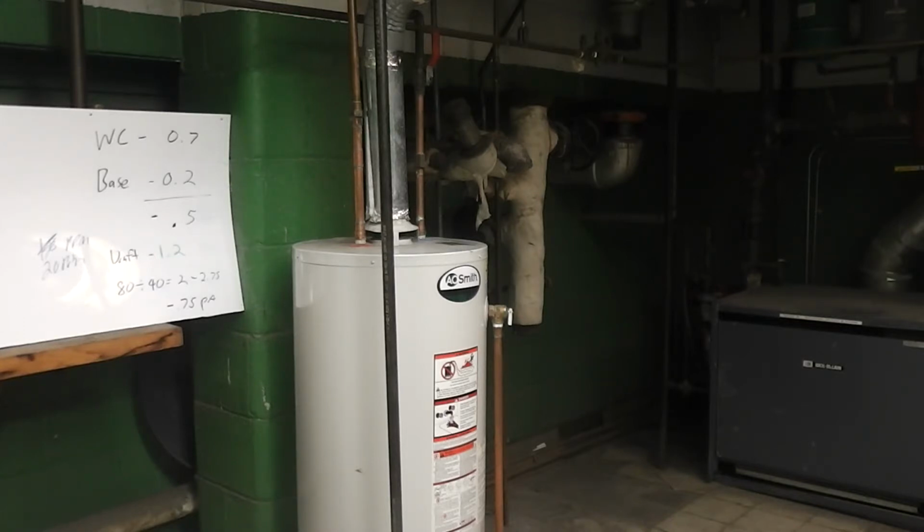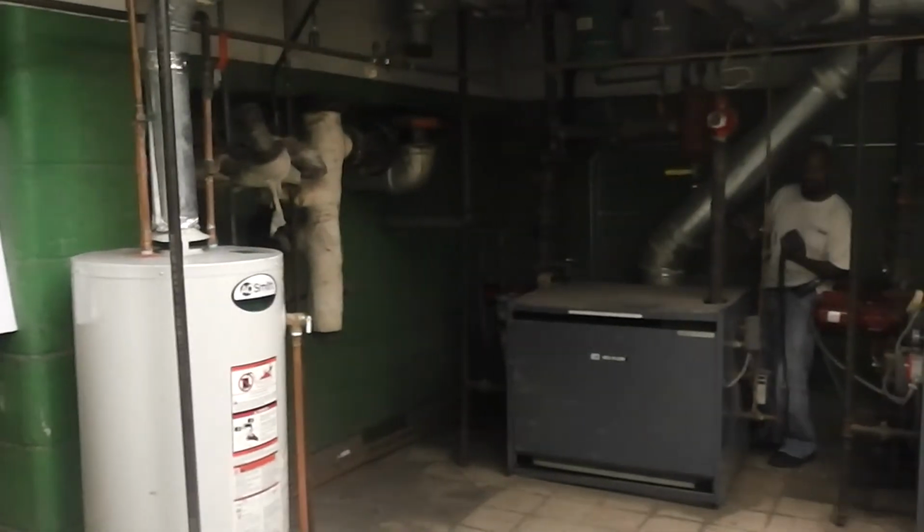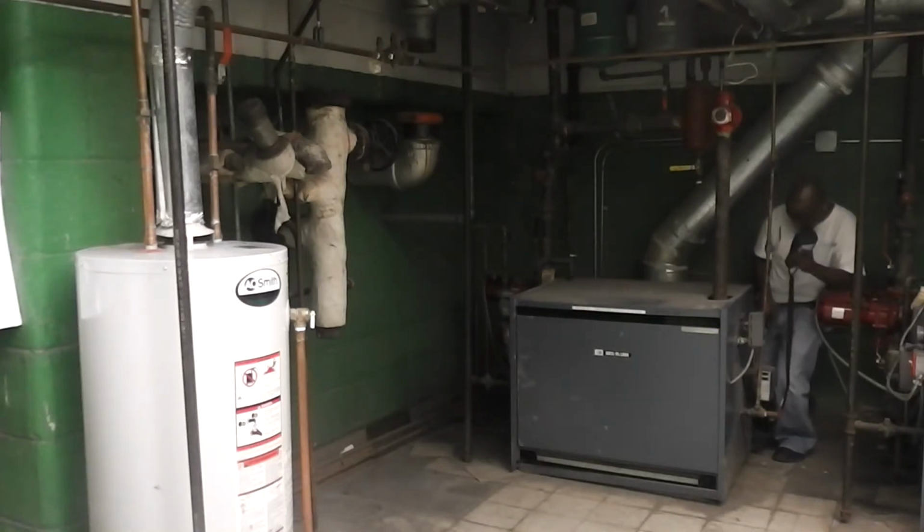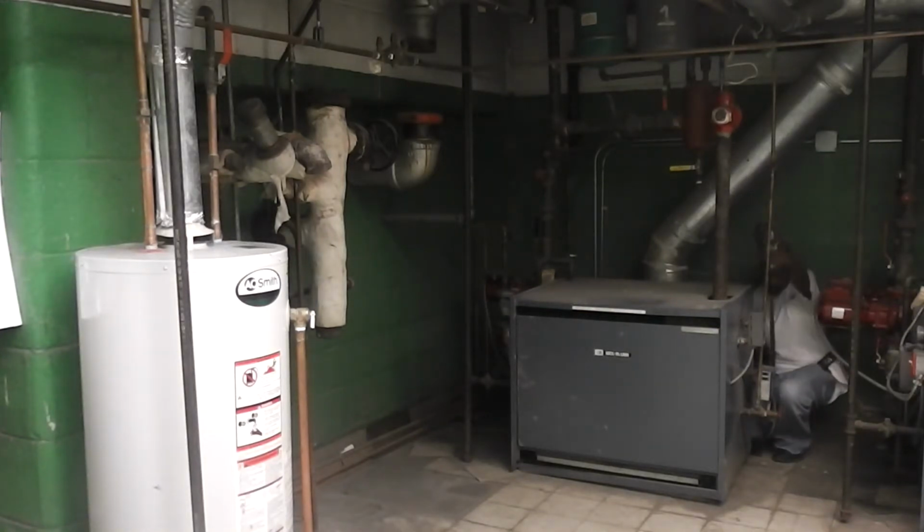So remember, I want undiluted CO. What does that mean? Undiluted CO, what does that mean? That means I'm going to stick this inside, past the diverter. And so far it's been past steady state, so I can initiate this test.